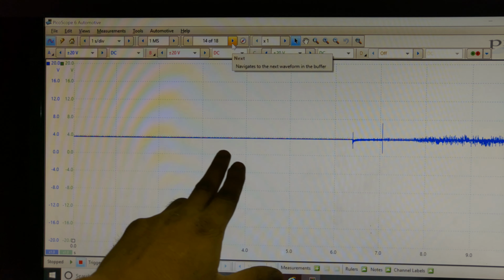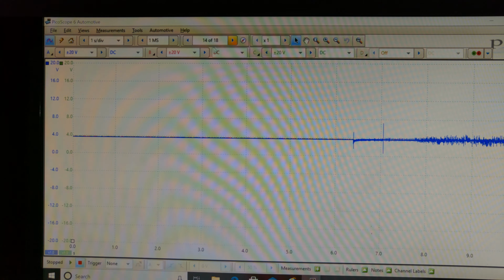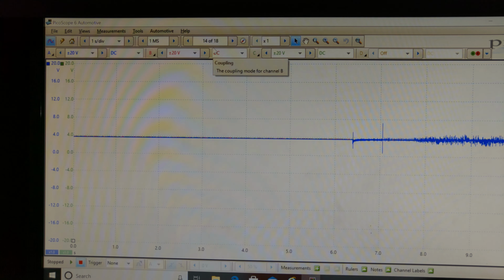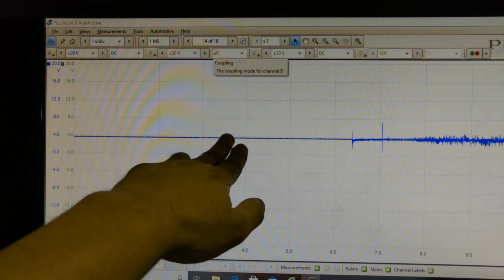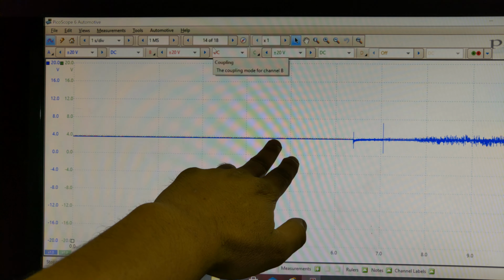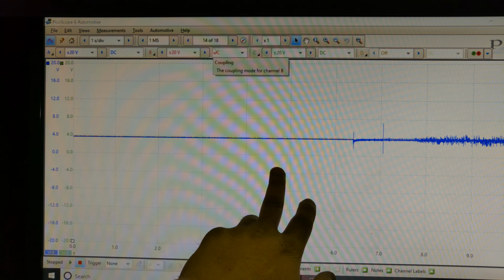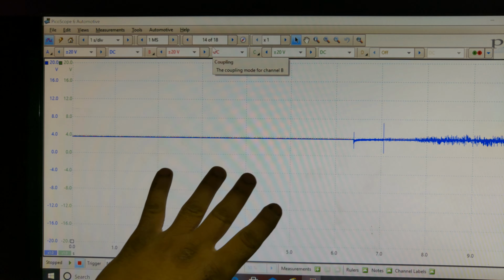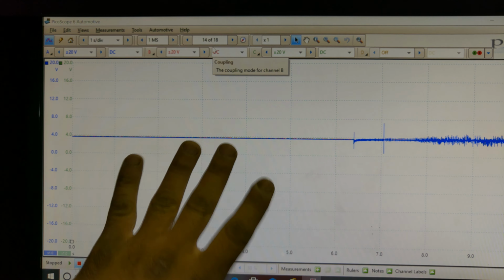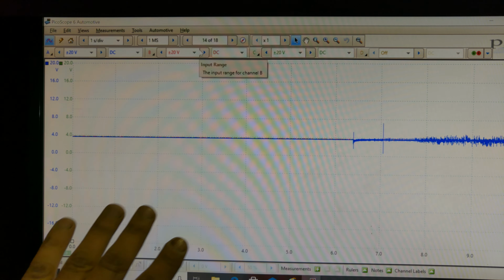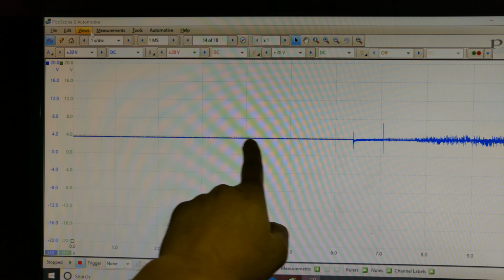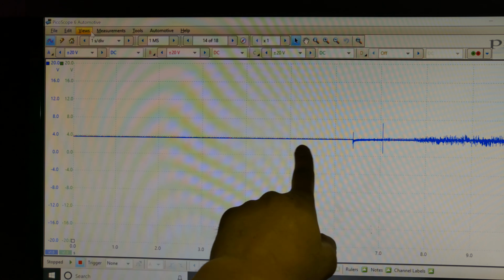It will stay at 4 volts for an extended period of time, usually about half a minute to, let's say, a couple of minutes, and then the computer will turn itself off and it will go down to 0 volts, which is not seen in this live picture here, but that's what it does. So 4 volts is a bias voltage, so we're going up here, 4 volts.